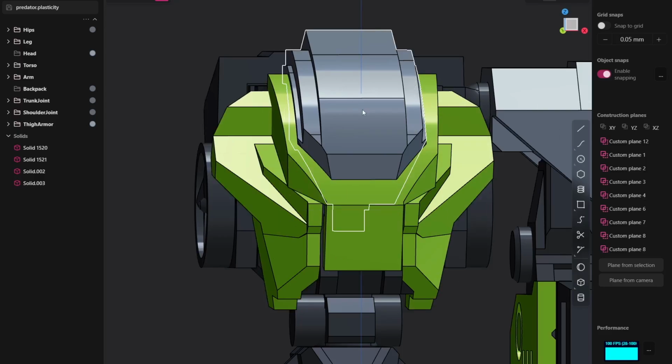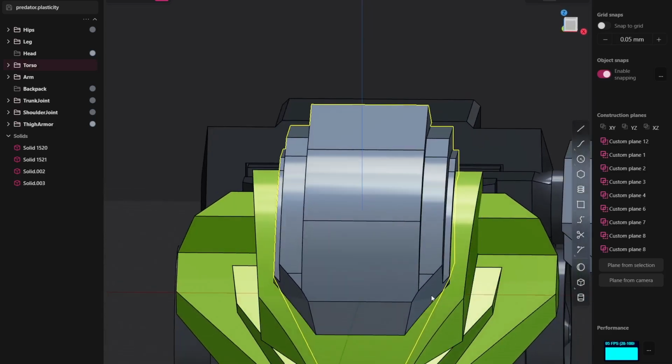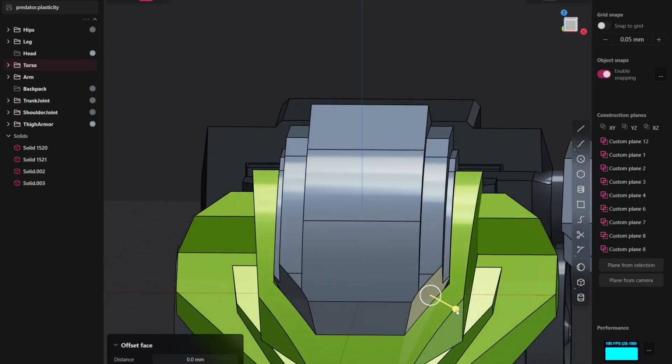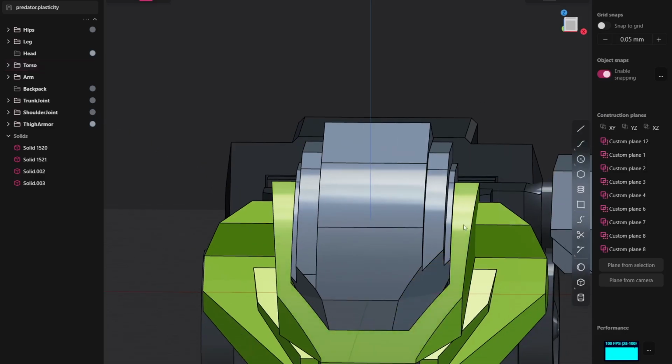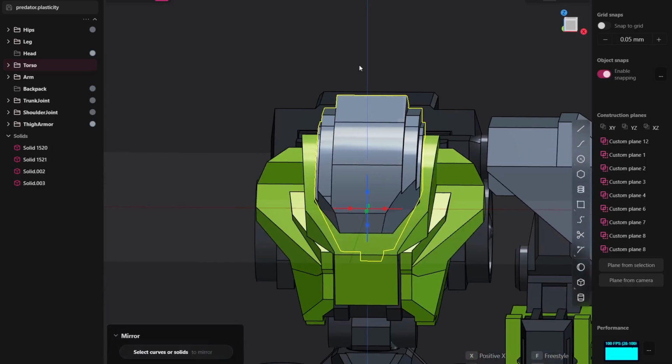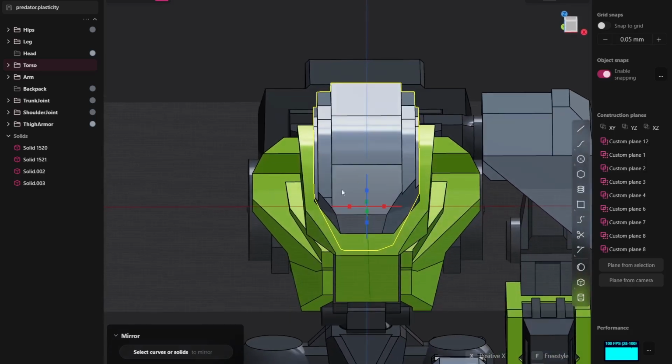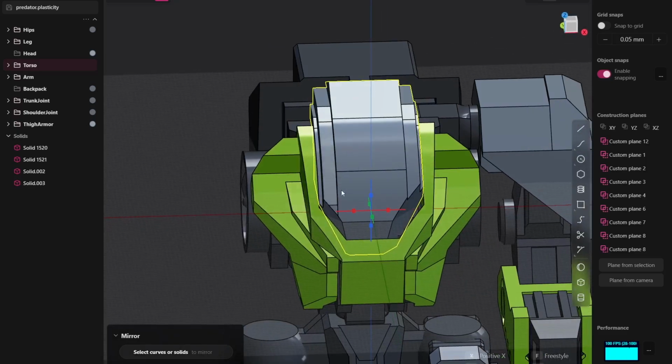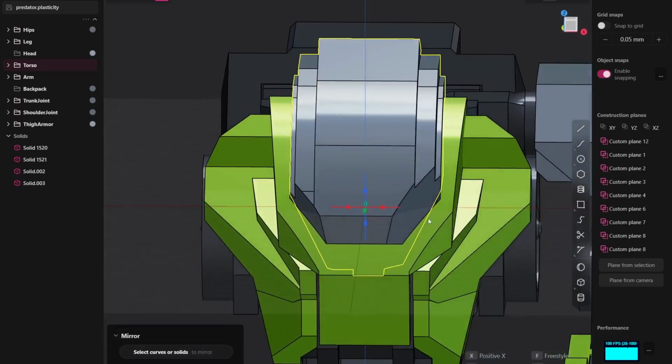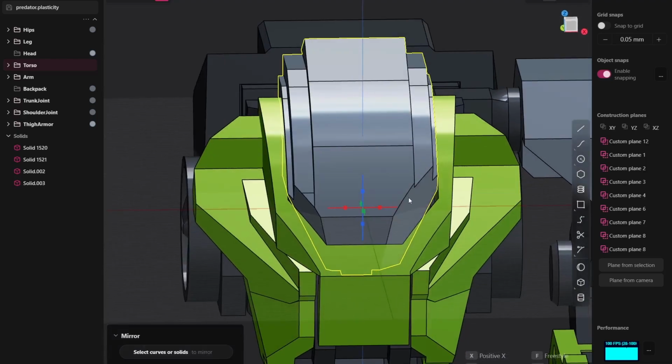So that's number one. But what if it's just one object? What if I apply a change to one side? Let's see, something like this. Maybe I want it a little more pointy. So I select the object and again, Alt X. By the way, notice that this only works in this case if it's being mirrored across the origin, because that's my pivot. We're going to see in a second what to do if the object is not at the origin.